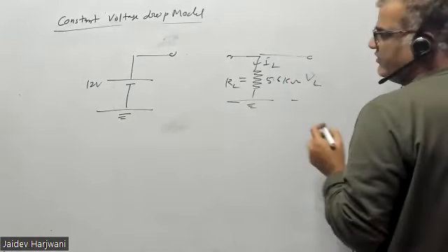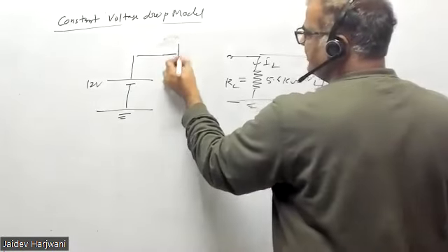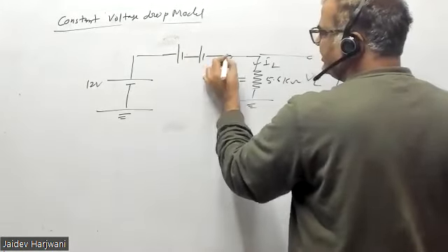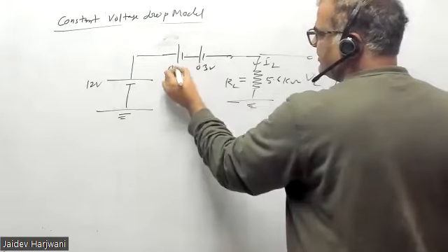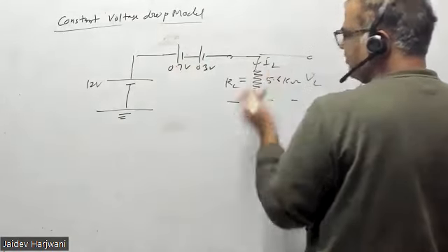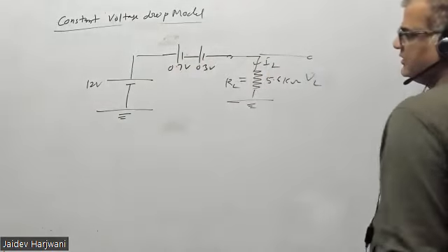And so it's greater than 1 volt. So both will conduct. So this will be replaced by 0.7 and 0.3. This becomes 0.3 volt. This becomes 0.7 volt. Now you can find what is IL.